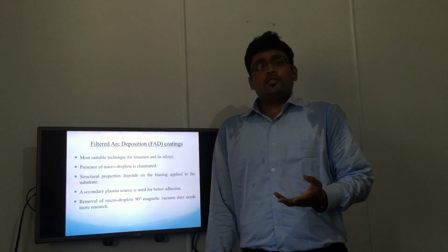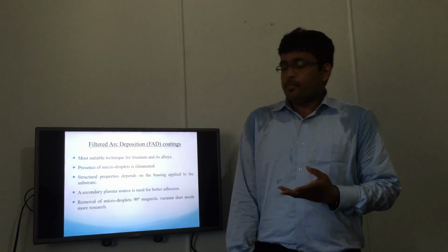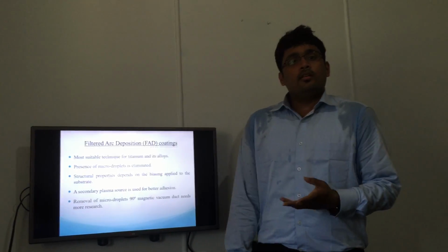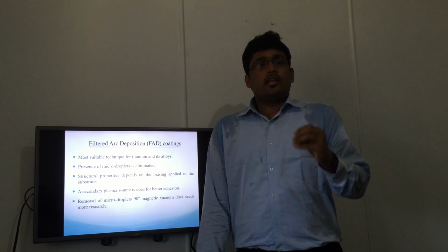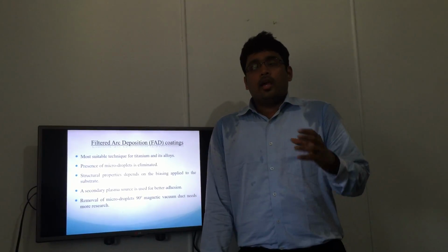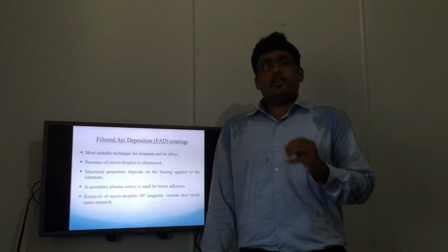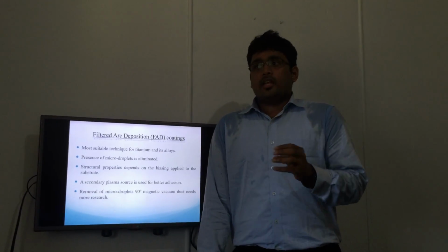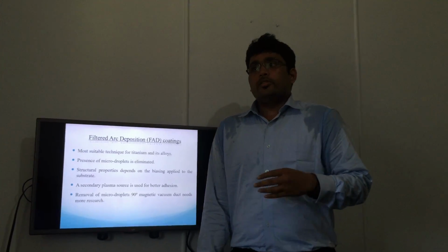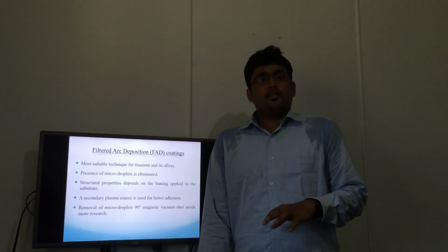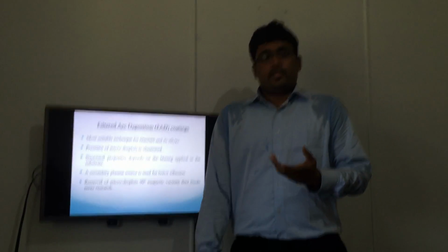First is direct deposition. Next is the ion assisted beam. In the direct deposition technique, the titanium material is directly deposited on the substrate. That is the direct deposition. And in the ion assisted technique, they use a secondary ion source. The secondary ion source generally uses a reactive or a noble gas, as it improves the properties.